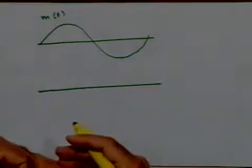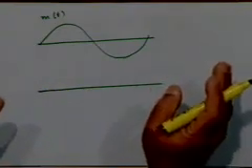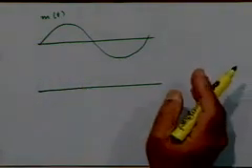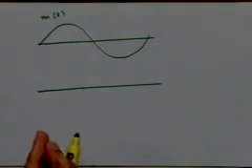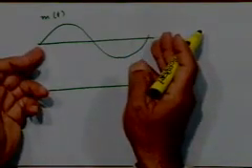We have discussed this earlier, but let's just quickly review this. The way to look at it is the following: cosine omega_c t is a high frequency carrier. That means the duration of one cycle of the cosine wave is much smaller than the duration of one cycle of the message signal, right? In this particular case, because this is a sine wave also. So we can assume practically that over one cycle of the cosine wave of the carrier, the message signal m(t) practically remains constant, because that variation happens too fast for it to vary significantly, right?